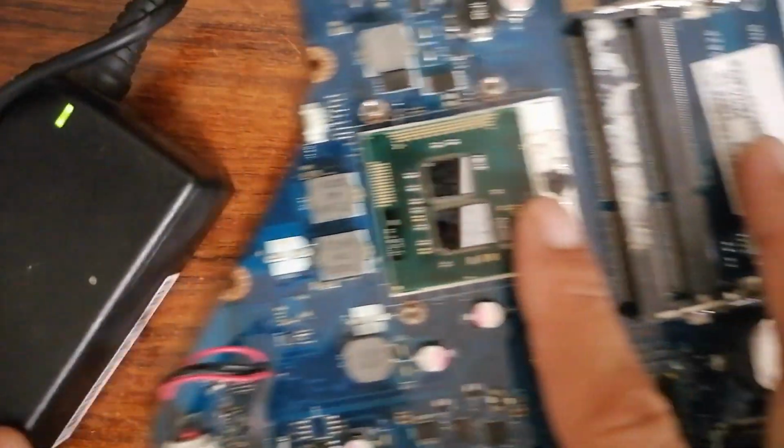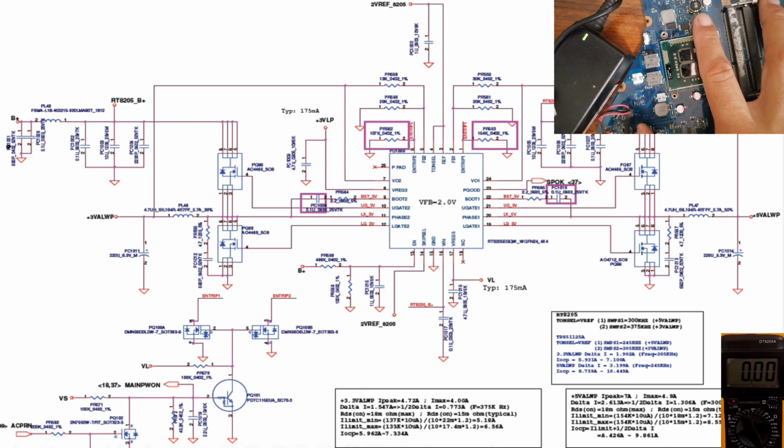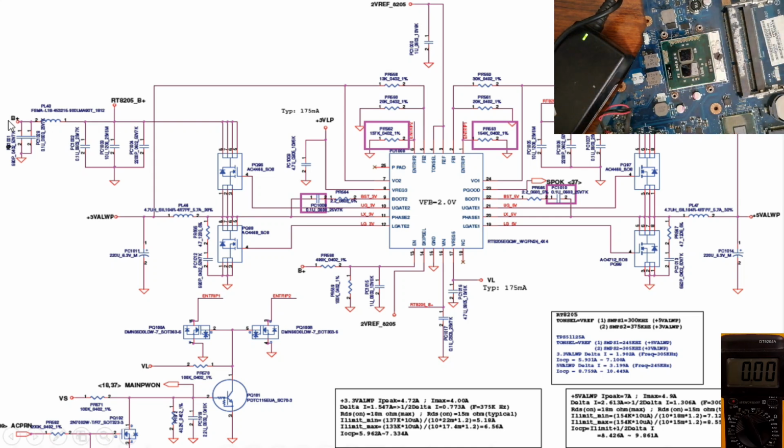Okay, so in this motherboard we don't have a short circuit, meaning if you didn't find 19 volts here, don't waste your time troubleshooting this circuit. So basically this is a good tip that, if you use it, you will gain a lot of time on repairs.